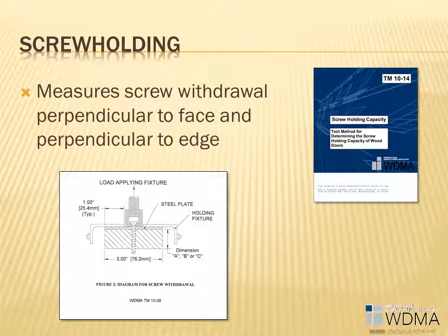Screw holding, measured by WDMA TM10, determines the ability of door components to resist the withdrawal of screws from other hardware components, perpendicular to either the face of the door or to the door edge.